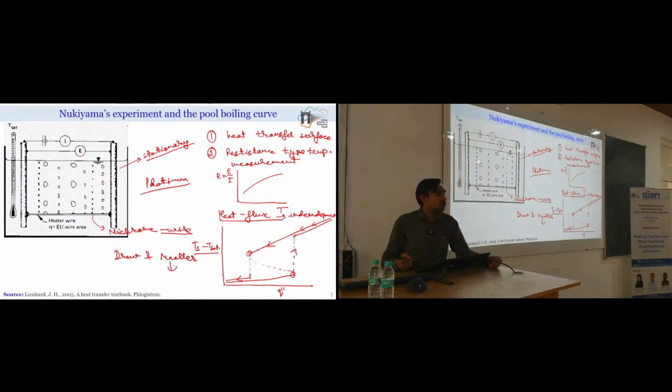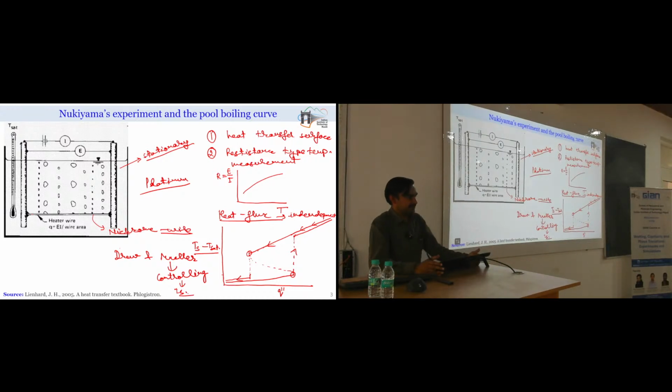They tried to perform the boiling experiment by controlling the temperature of the heating surface. So, here the controlling parameter was the temperature of the heating surface. How did they control the temperature, because controlling the temperature is quite challenging? Once your heated surface is in contact with the liquid phase, the rate of heat transfer will be faster, and the input heat supply has to be increased in order to maintain the same temperature. But if it is in contact with the vapor, the rate of heat transfer will decrease, and to maintain the wire at the same temperature we also have to decrease the input supply. This phenomenon is intermittent, sometimes quite fast and chaotic, and that is why it is extremely difficult to control the temperature.